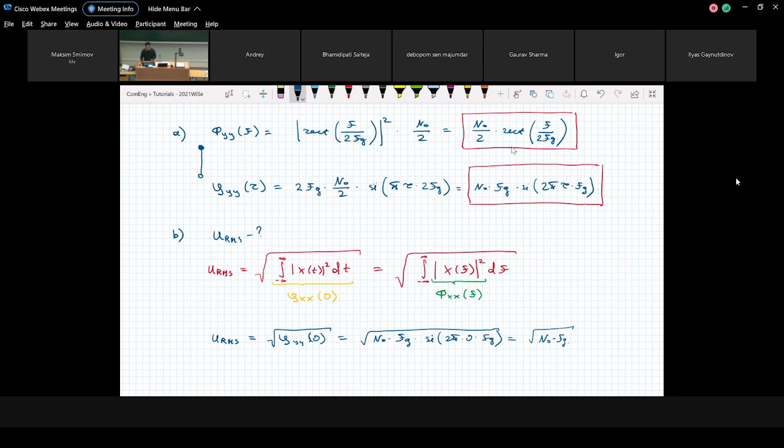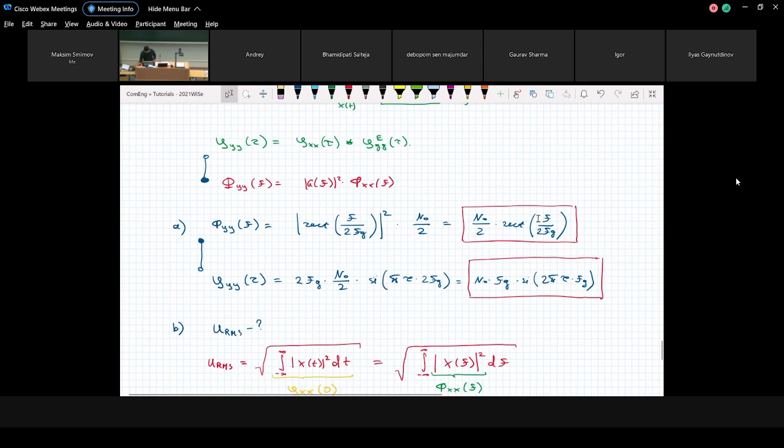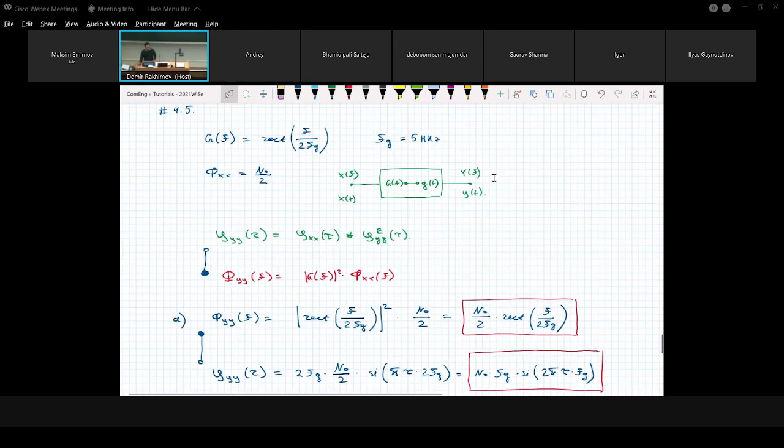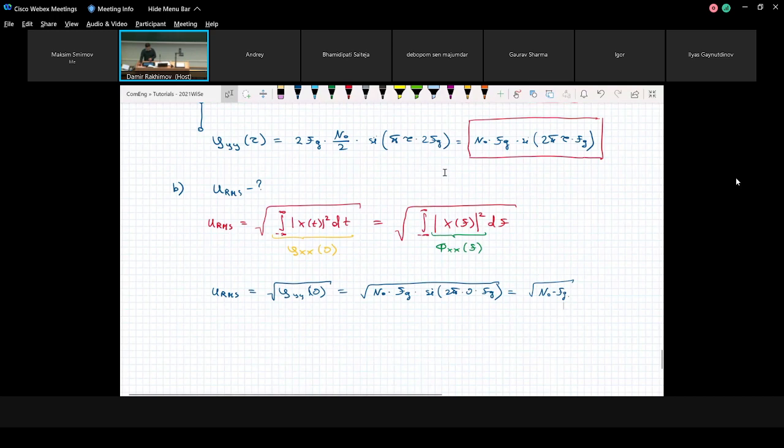And you see here that we don't have a DC component. Do we have a DC component for this example? We have noise. Noise, I mean no DC component, because the mean value for noise is zero. But here you see that even if I don't have a DC component, you have a non-zero variation. And this variation is proportional to the bandwidth that you have, because the larger the bandwidth, this parameter fg, the larger the RMS value you have at the output.